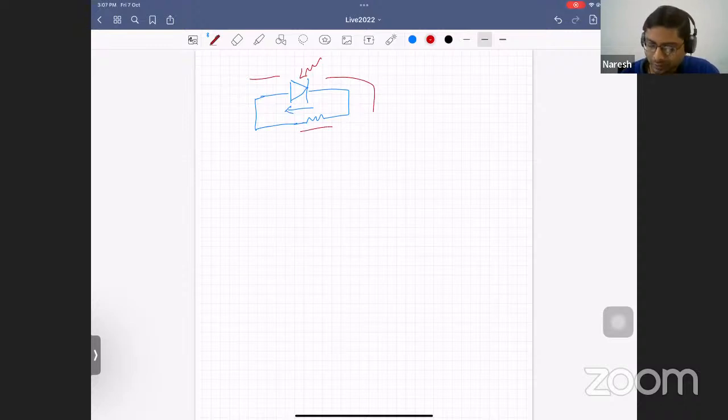And if this is some voltage V, that should satisfy the current equation, right? Because if you have IL, what should be the expression? I naught exponential QV by KT. If I call it VA, okay, let's not call it VA because we are saying it's not applied. So QV by KT. All right. So this voltage drop V is what falls across the resistor, but we are not applying any external voltage. Did I clarify, Manojit? Any questions further?